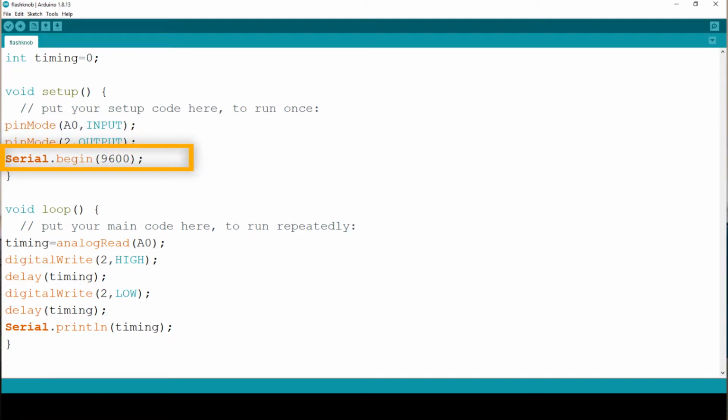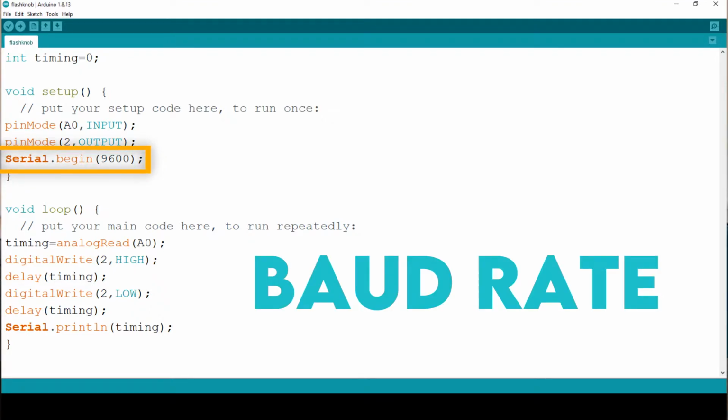In line 7, I initialize the serial communications. Serial communications are how the Arduino communicates, either through the USB port or through pins 1 and 0. Running the Serial.begin method tells the Arduino that we're going to be using serial communications and that it should initialize this communication line with whatever devices it'll be communicating with. The input variable for this is called the baud rate, which is the communication speed. There are many options to choose from, but it's best to stick with the standard. I recommend 9600 as it's the default and works well for most applications.